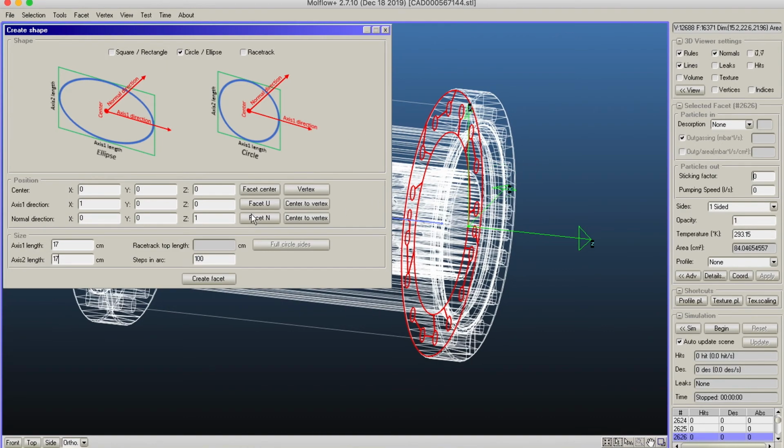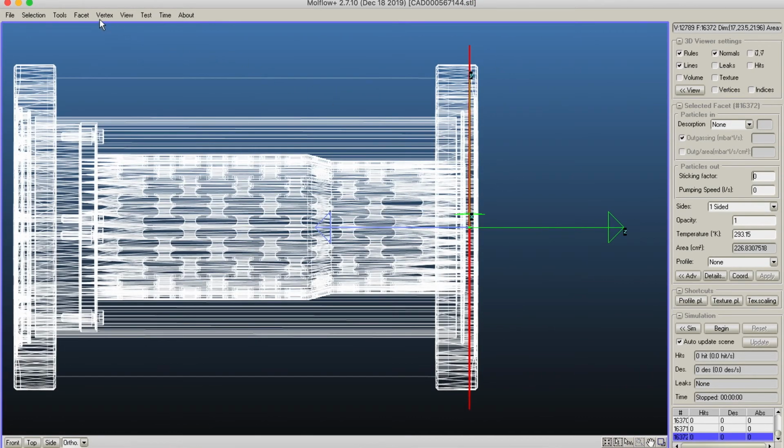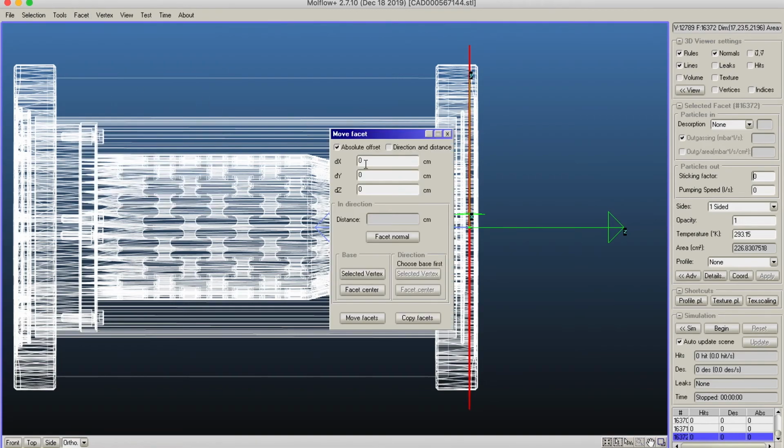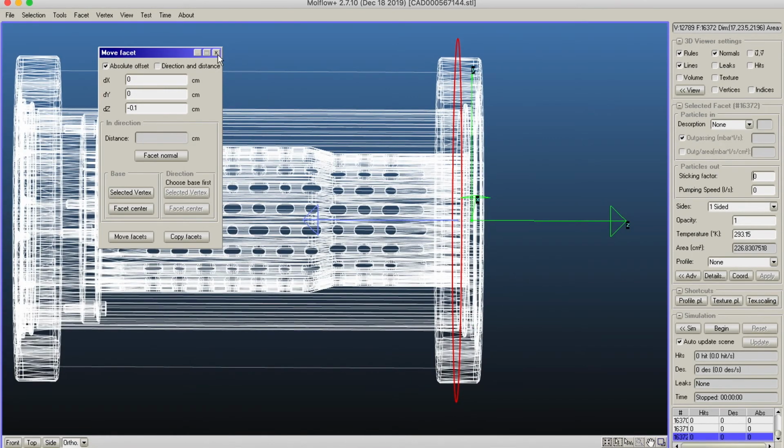And then I'd like its normal vector to face the minus z direction, otherwise the coordinates at 0, 0, 0 are correct. So I've created my plug, and to make sure that I plug the whole geometry, I will just move it down a little bit to the inside. So basically I'm gently placing it here, so that way it crosses my geometry.